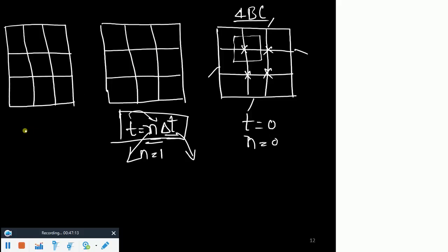So we were talking about this physical time, and similarly if you talk about t equals 2 delta t. Now you see, physically you come up at t equals 0.2 second. So you have to look at, as far as that assignment is concerned, why I am discussing this thing, because I have given you an assignment. You have to look at temperatures at certain physical times. I ask you to find out temperature at certain nodes at certain physical time. So how can you determine how many time steps you need to perform? Using this relation. You understand that? Okay.